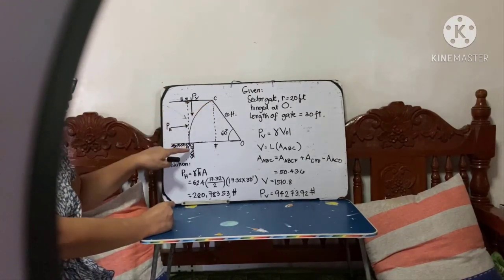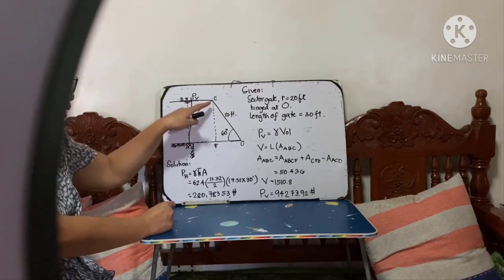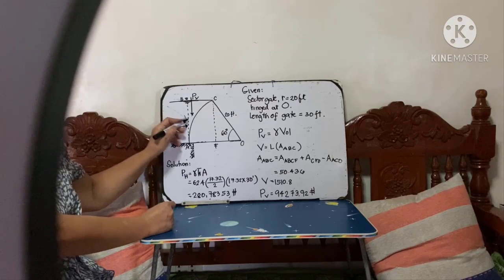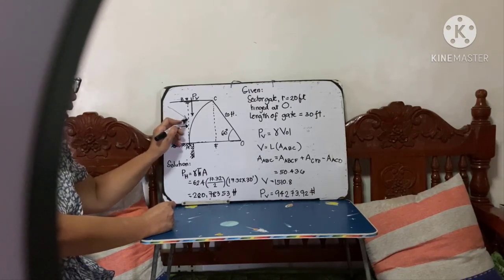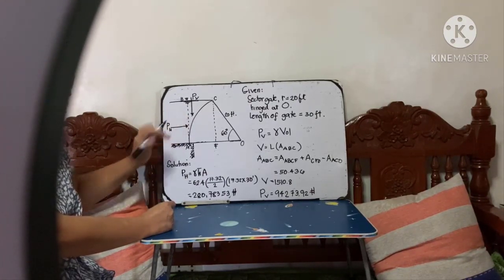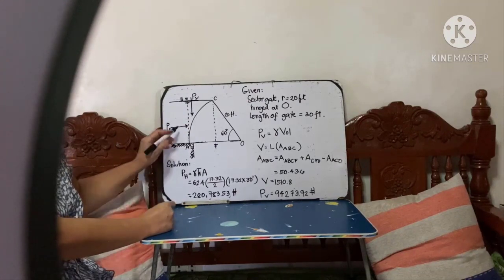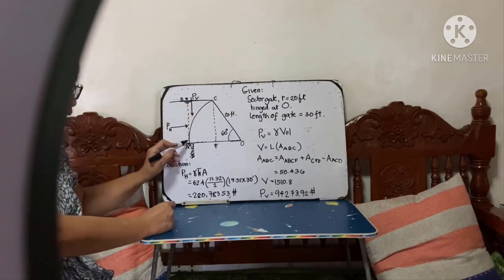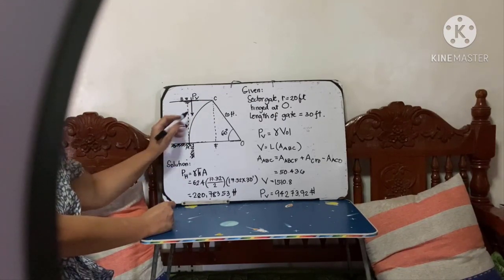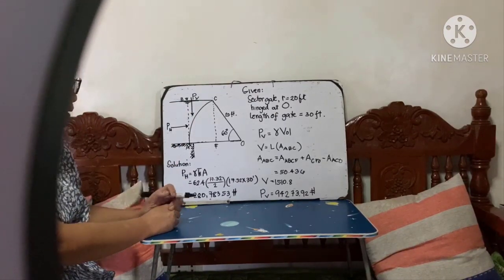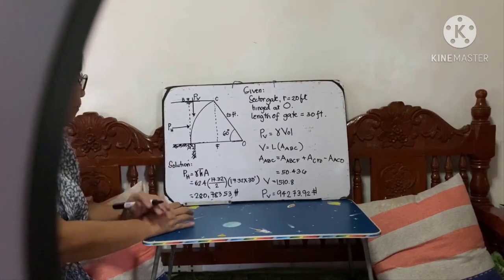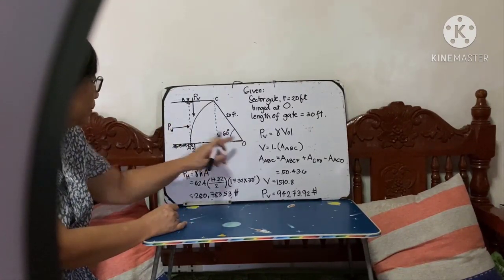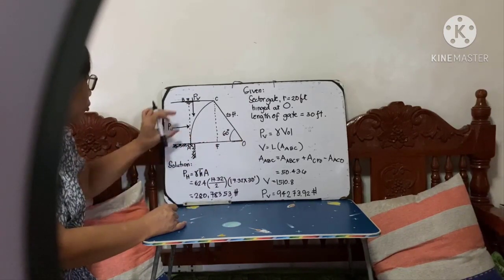But our surface is curved. It is a curved surface, so the resultant is harder to get because it is curved. So the better way is to resolve the total pressure acting on this curved surface into its horizontal and vertical components. That is the easiest, because later when we take moment about O, we can see their moment arms.